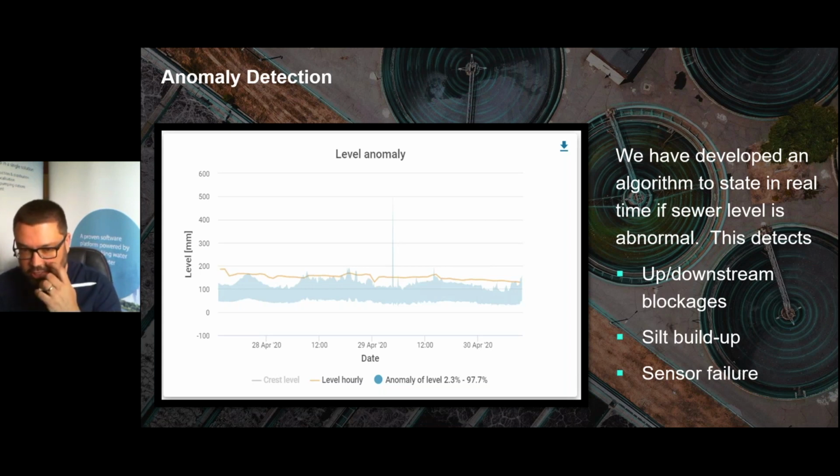So as we start to see changes in climate where we don't necessarily get that prolonged, slow rainfall that we used to get in the UK, for example, you might get short, sharp rainfall events. And what this means in these prolonged dry periods is you get a buildup of dry matter within your sewer network. And that dry matter gets flushed out. It's called the first flush with the rainfall.